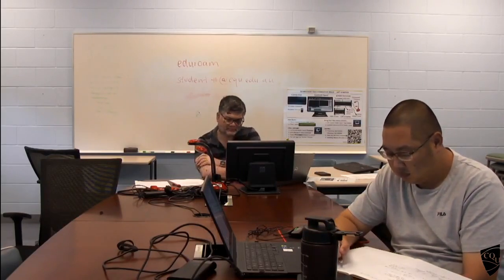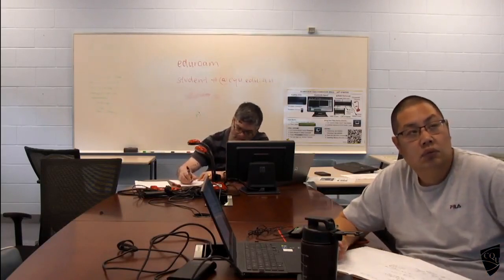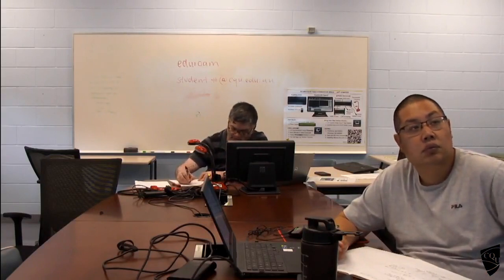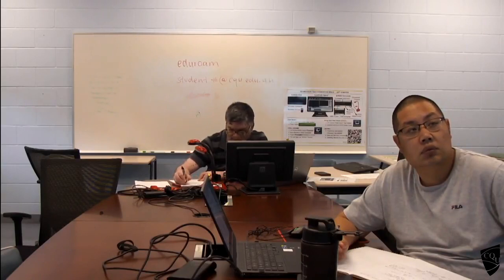Load you already have, length you know, E value you should be able to find, but the problem is I, the second moment of area. To find I, you need the neutral axis, because I is about the neutral axis. So those who forgot the neutral axis, the I value is B D cubed upon 12.